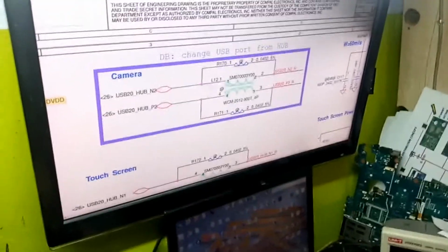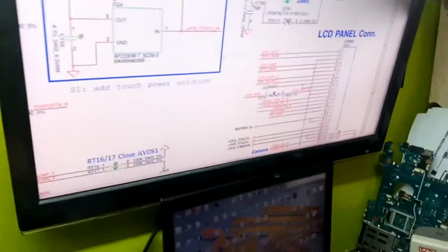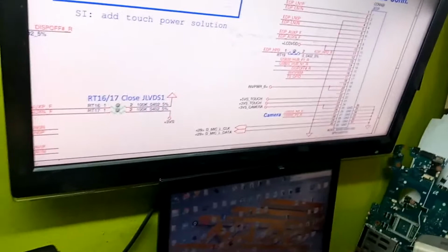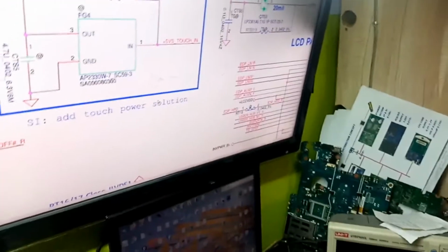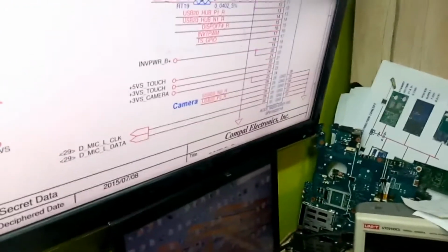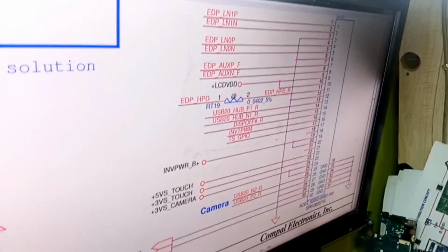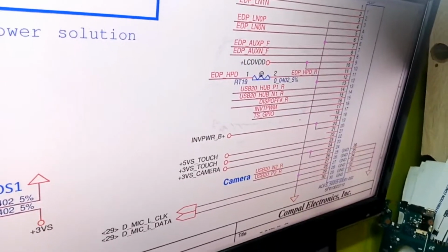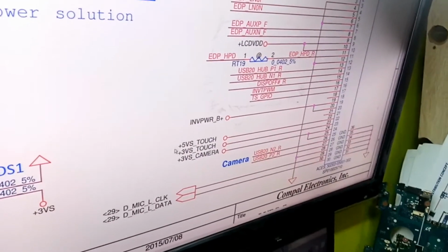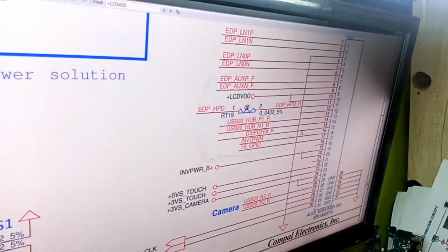Here, what I'll do next is I'll check what are the necessary requirements again. Remember I said those ones are the primary ones, so I'll go for the secondary requirement of this LVDS section for backlight. So here I'll check what is the value on my pin number 15 and 16. This is display off and inverter PWM. And this particular pin 20, 24, 25, actually these are not important, but one can just confirm for confirmation sake. So I'll go for this first, this pin number 15 and pin number 16.